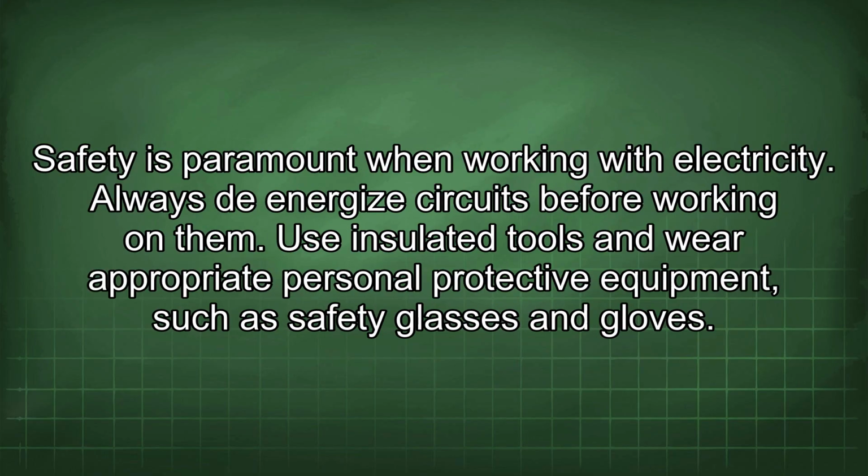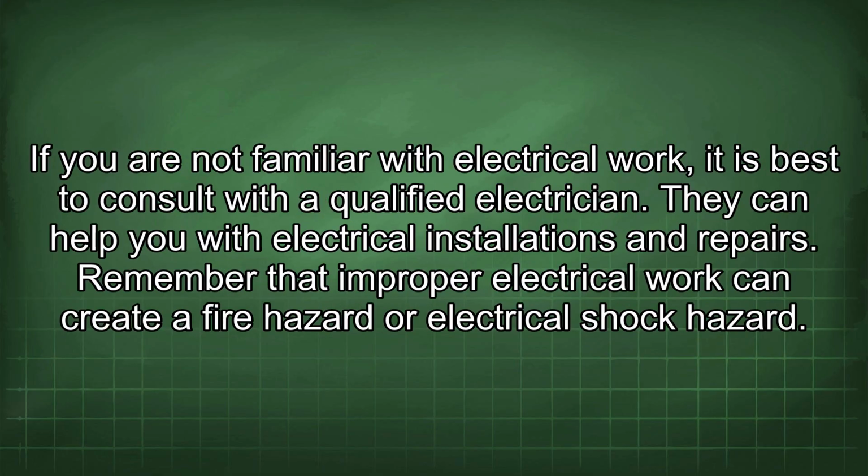Safety is paramount when working with electricity. Always de-energize circuits before working on them. Use insulated tools and wear appropriate personal protective equipment, such as safety glasses and gloves. If you are not familiar with electrical work, it is best to consult with a qualified electrician. They can help you with electrical installations and repairs. Remember that improper electrical work can create a fire hazard or electrical shock hazard.